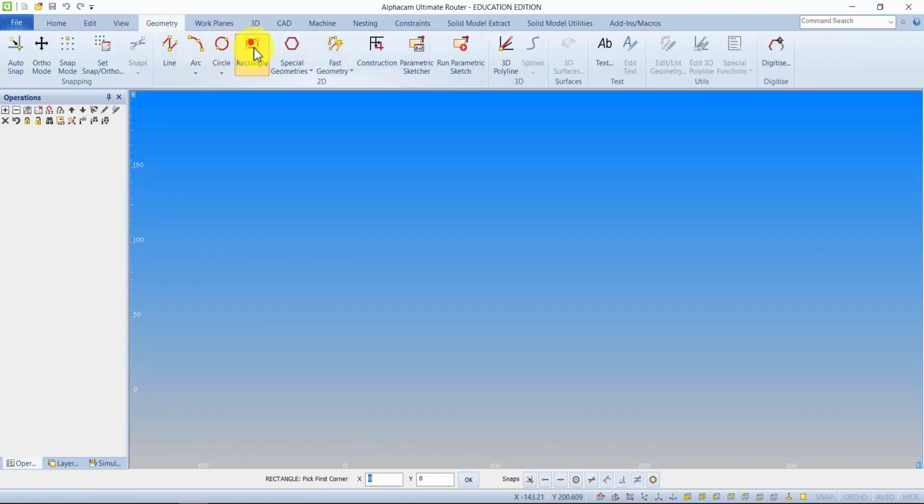I'll begin with just a simple panel, and I want this panel to be approximately the size of an A3 sheet of paper, let's say. So let's set the first coordinate to be 0, tab 0, enter, and the other coordinate to be 420, tab 297. Remember that a sheet of paper sized A3 is 420 by 297. I don't want that ghost tool yet, so I'll just tap Ctrl and G to get rid of it. And I'm going to use this as my sheet.